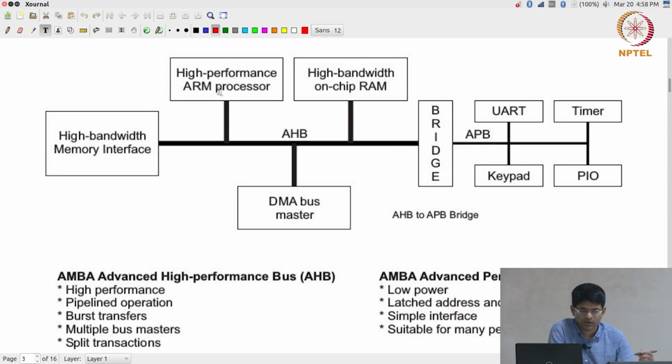Okay. Now, we will see later how this can actually be useful, how you can have multiple masters interleaving and trading usage of the bus, so that the effective utilization of the bus is very high and each of the masters can be kept busy to a large extent.